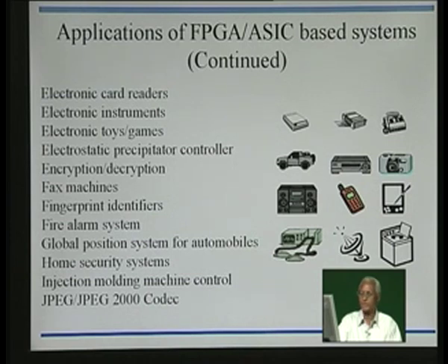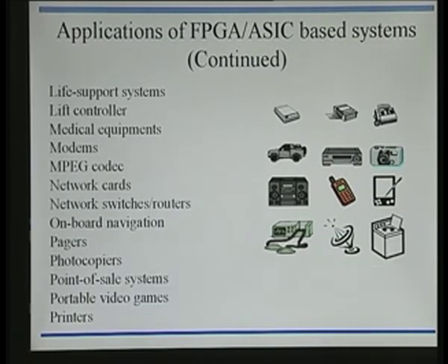And then we have already seen a camera example. JPEG codec is also one such. If you want a still picture, you need JPEG, and if it is DCT based, which we have already seen, you need JPEG, and if it is DWT based, that's discrete wavelet transform based, you need JPEG 2000. If you want motion pictures to be processed in a JPEG 2K like thing, you have motion JPEG 2K for the same, and there's plenty of scope for you to develop algorithms, architecture, and finally implementation as FPGA or ASIC.